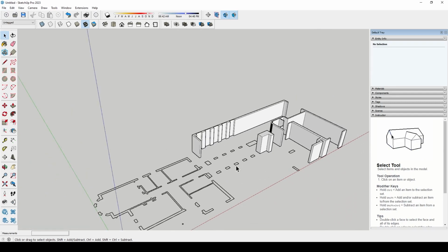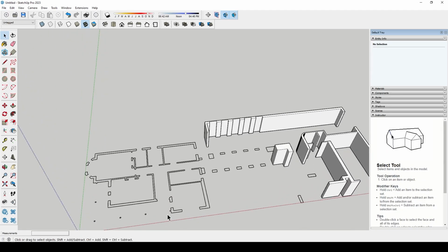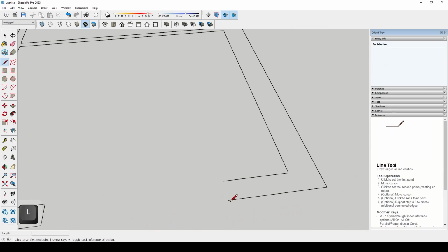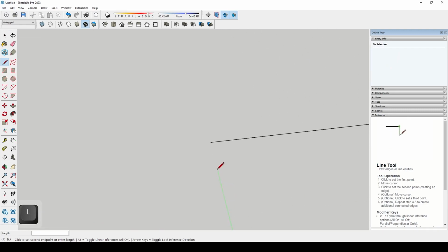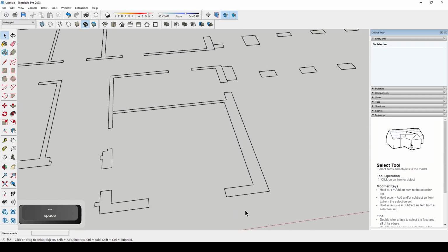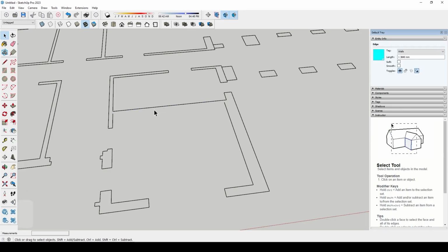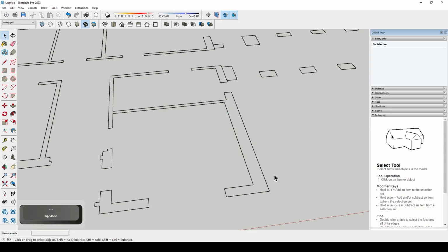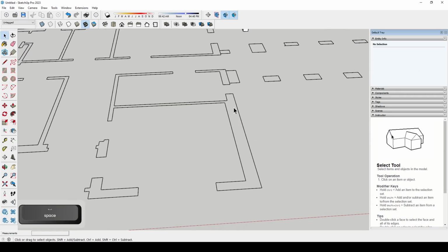What I want to do now is show what happens when a wall doesn't work quite successfully, and we need to figure out what is going astray. So let's say, for example, you can't see it, but in AutoCAD, we've got a line that doesn't quite go all the way to where it should be. From the naked eye, that looks like it's going all the way there. We delete this line over here and say, okay, straightforward, do the same technique Chris told me. I go over here and, oh, what? Nothing's happened. It doesn't turn white. I can't double click inside anything. Uh-oh, what do I do?